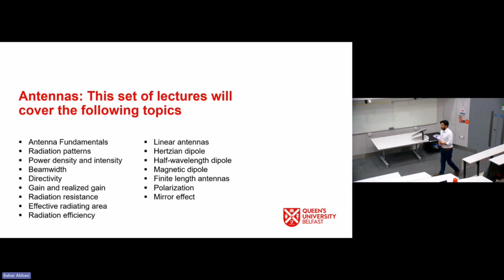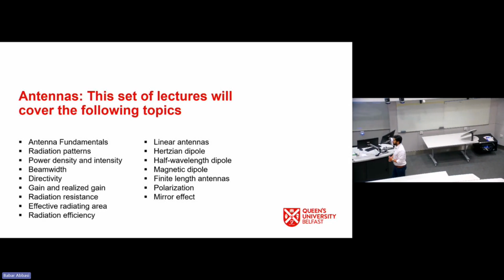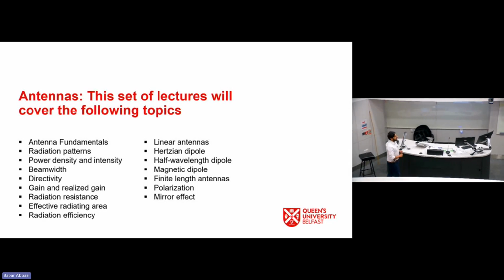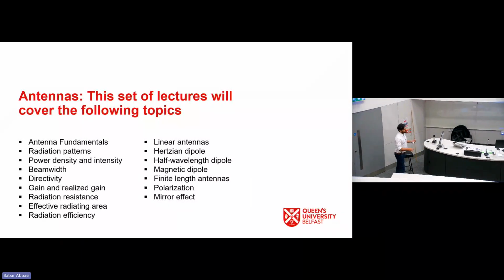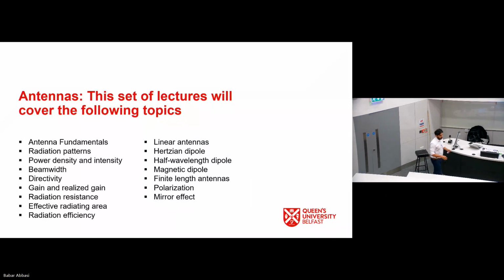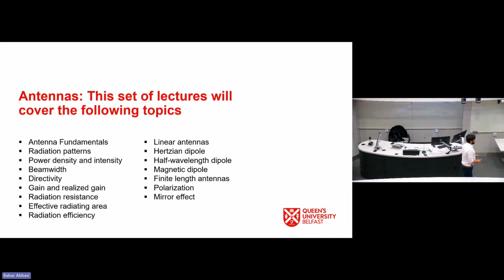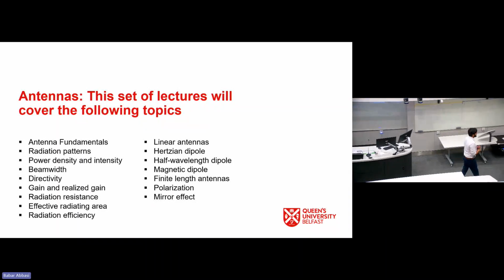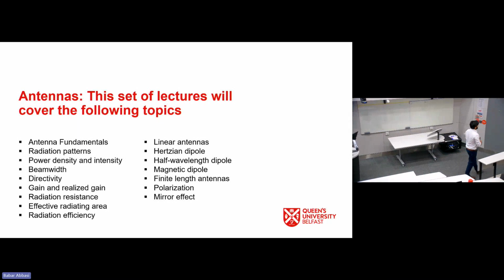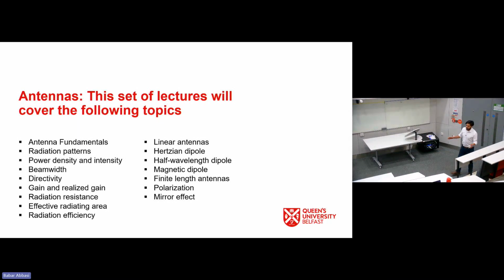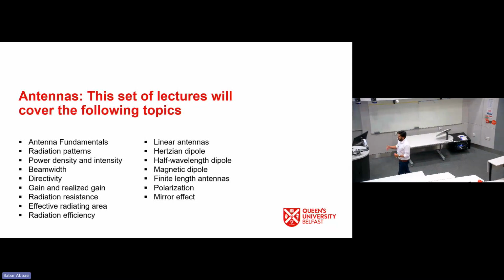We also established that 100% efficient antennas are not available in nature. It's just not possible to get a 100% efficient antenna. That's why whenever antenna efficiency is more than say 90% for most important applications, we are okay with it. If for some particular antennas in very harsh environments, antenna efficiency is more than 50%, it's still okay. It works for us. A lot of energy gets wasted, but we don't really care about that kind of wastage